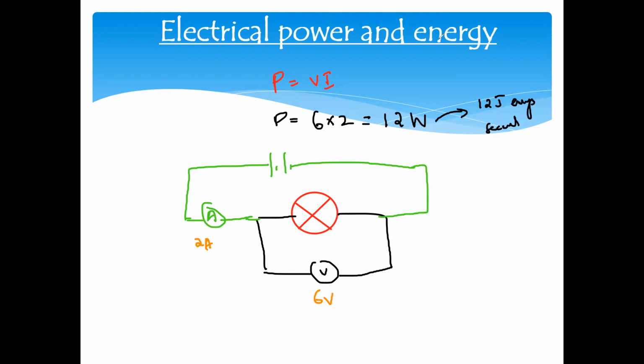And if we want to find the resistance, how do we get it? Resistance is actually a ratio between voltage and current. So voltage divided by current gives us resistance. The voltage is 6 and the current is 2, so 6 divided by 2 equals 3 ohm. So resistance is 3 ohm, which is a low resistance, so it has a low tendency to resist or stop the charges, whereas the power is 12 watt, which means it can consume 12 joules every second.